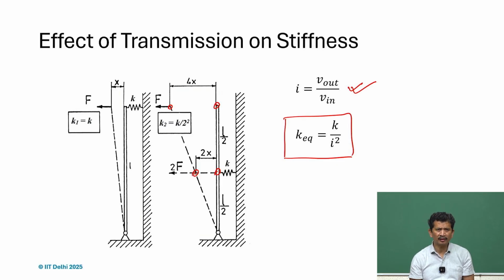So, there is a huge impact on the stiffness, and if we know this, then we will also check it in the design. Just moving the spring can affect the overall performance. If that k equivalent is different, all the vibration requirements, your omega 0 values, will all get affected because of that. And if we know this, I think by now we should be able to appreciate why certain phenomena happen that were not expected earlier.